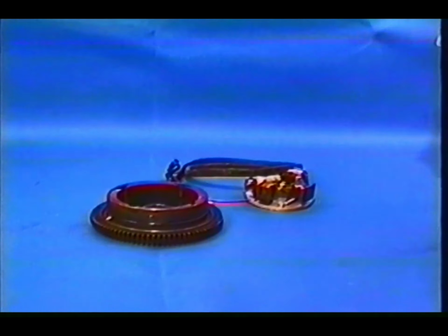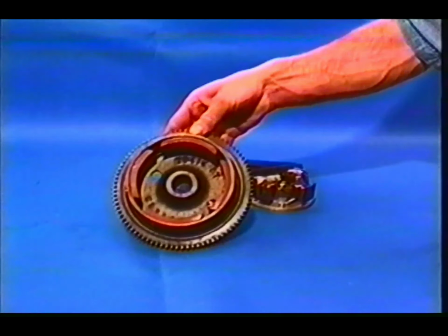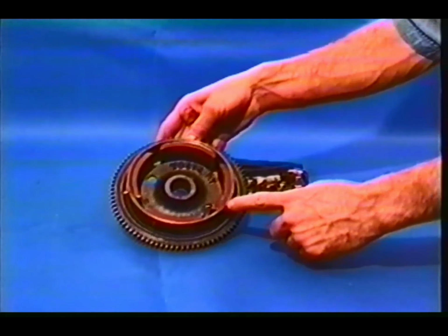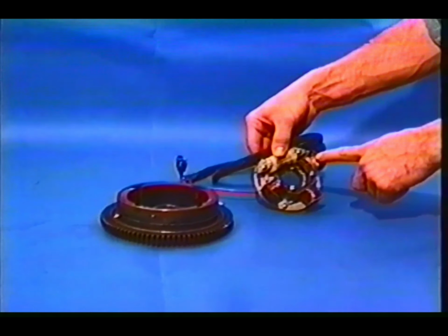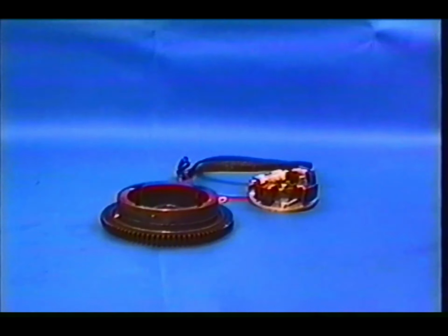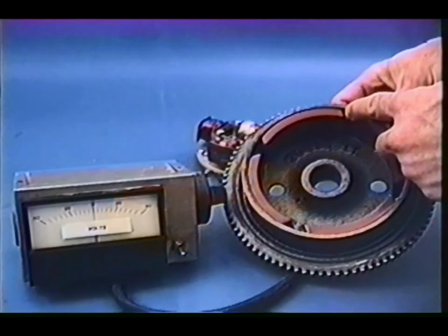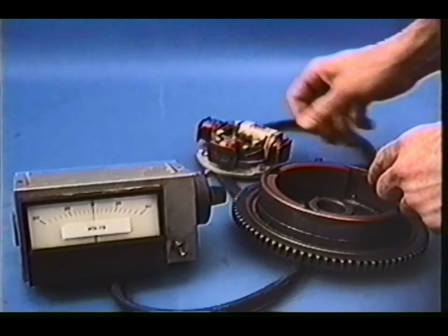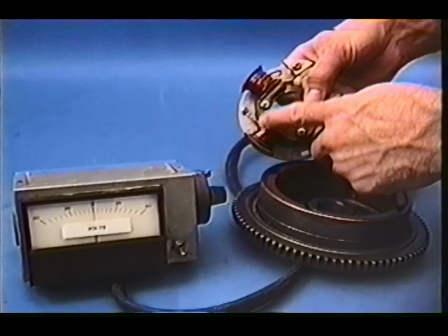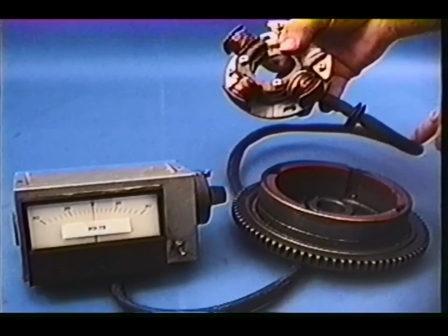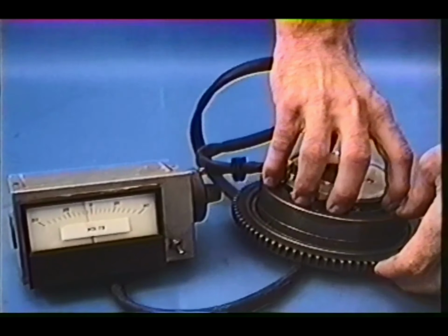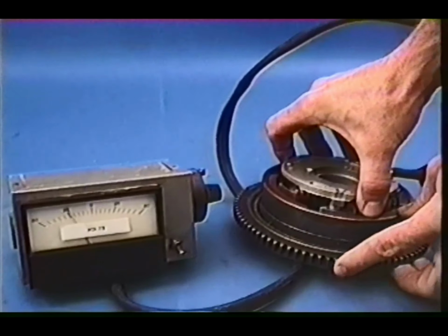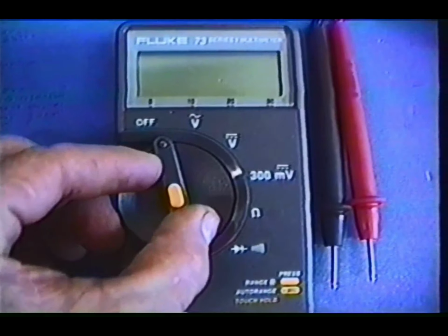The charging system on Polaris products uses a highly efficient alternating current, or AC, generator to create voltage. An AC generator consists of a flywheel with magnets and the charging coils or stator assembly. When a magnet is passed by a coil of wire, voltage is induced in the coil through a phenomenon called electromagnetic induction. If there is a complete circuit, current will flow within the wire. When the direction of the magnetic field reverses, the flow of current induced in the coil is also reversed.